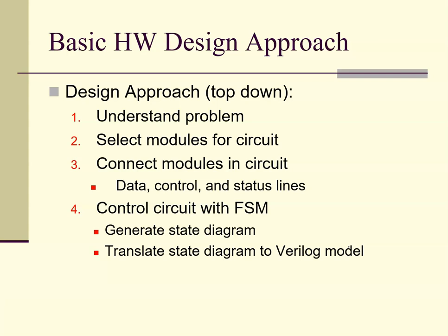And at that point, it's ready to create an FSM. So what you're going to do here is start with a state diagram. You have a state diagram, translate that state diagram to actually Verilog code and put it in your project.